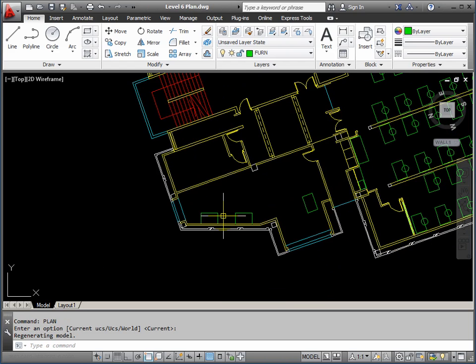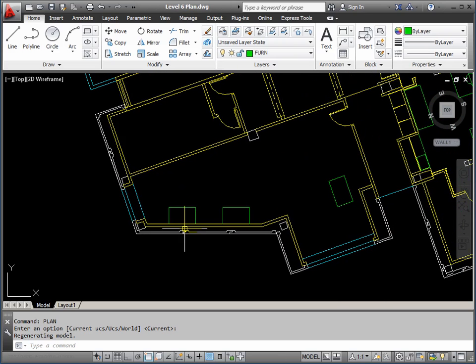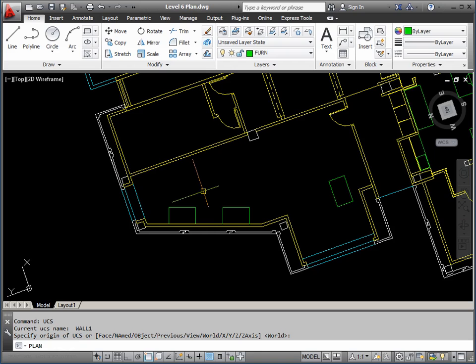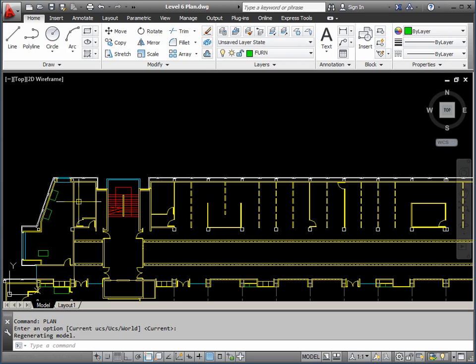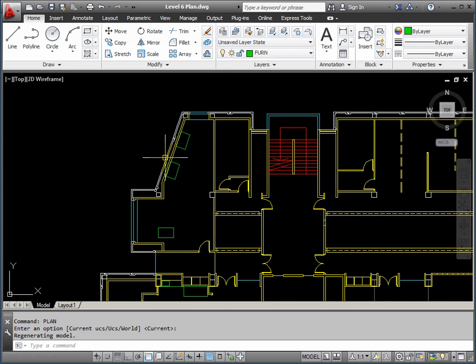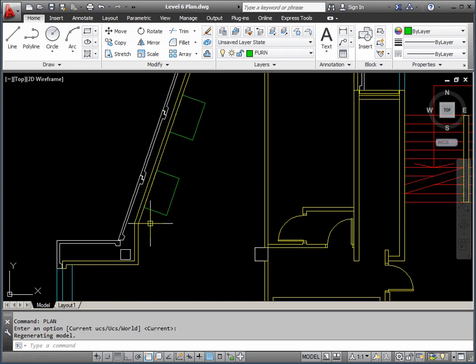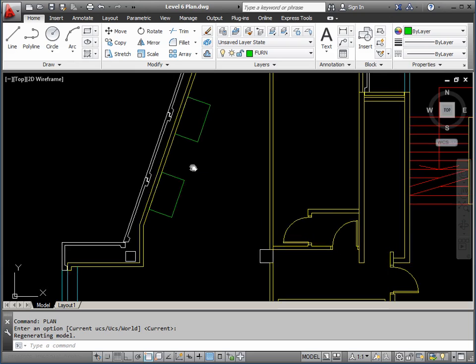It's a good habit to get into. If you think you're going to use that again, save it into the drawing. It saves you doing the setup and possibly getting it wrong. Remember the backtracking is UCS, return twice, plan, return twice. Everything goes back to normal. So that's a much more sophisticated way of working in relation to something that's at an awkward angle. Less chance you'll make errors. The way we did this before, there is chance for something to go wrong, something that doesn't end up perpendicular. It's much more likely.